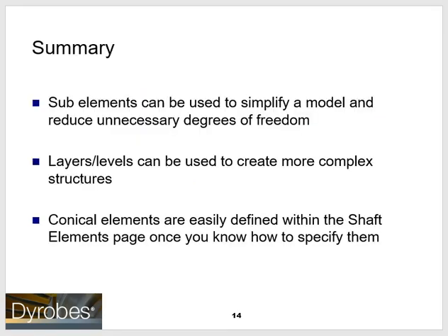To summarize what we've talked about, subelements can be used to simplify a model and reduce unnecessary degrees of freedom. Layers or levels can be used to create more complex structures, and conical elements are easily defined within the shaft elements page once you know how to specify them.